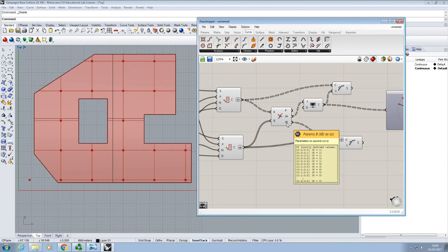And what we want to do, essentially, is keep that last set of addresses. So what we've got here is 0000, 0001, 0002, and so on, all the way down to 0405. That last number in that address is the index of the item going into B. So rather than flattening the outside, the last set of branches in here, we want to actually flatten the innermost ones. So we've got everything in a separate branch depending on that last number.